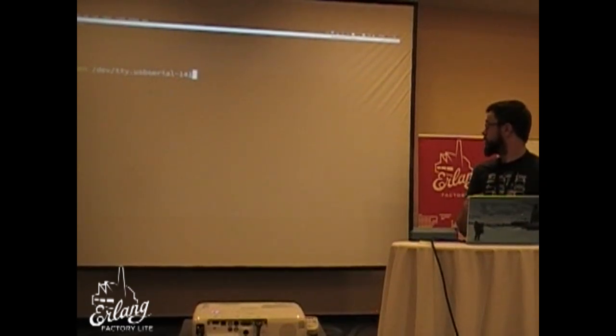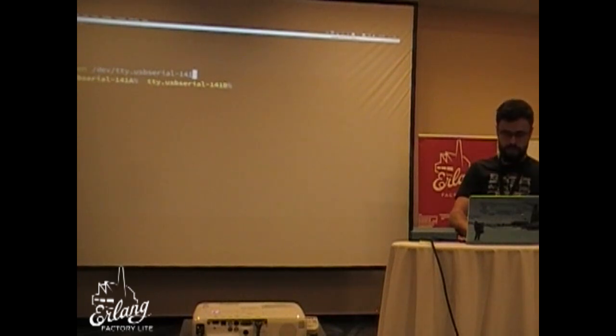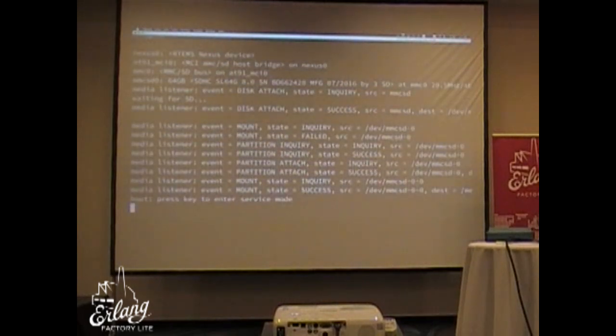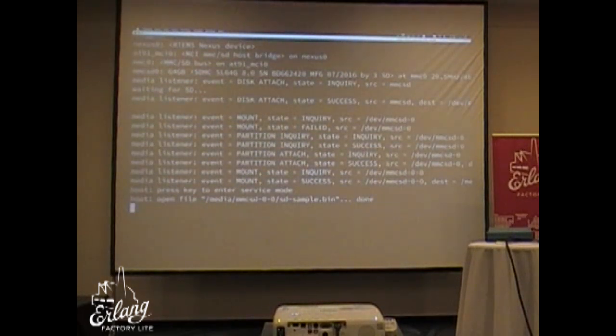So you can talk to this serial device, and you can use screen to do this. And in this case, I'm also setting the baud rate to get the right input/output. Otherwise, you just see garbage here. And this will drop you into a... I thought it would drop you into a console. Yeah, there we go. So this is the boot process.